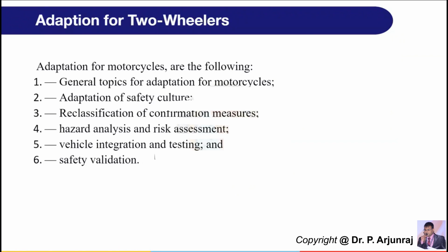So here, when you're developing the cluster, you have to do the design verification plan, not only with respect to hardware application, even the software application also to be taken into consideration. And you have to integrate both the hardware and the software application, and then you should test it. And you also see what happens. I will give you one example. If the original speed of the vehicle is 80 km/h, but it is showing only 40 km/h in your cluster, then there might be some fault.